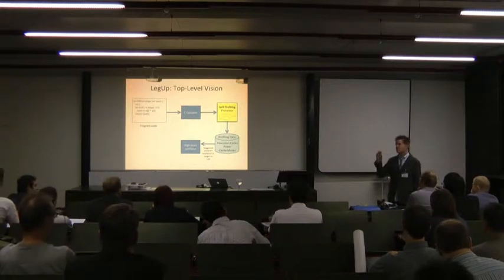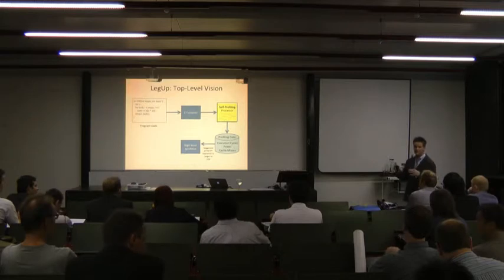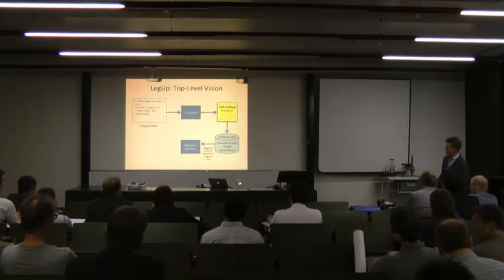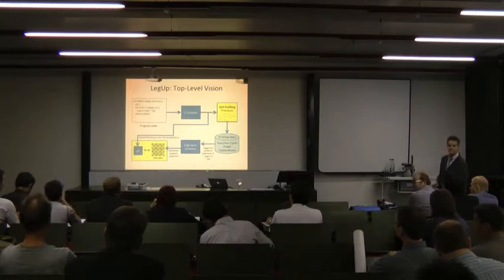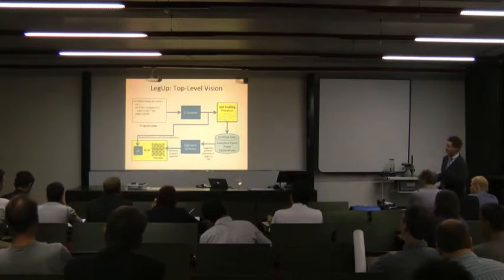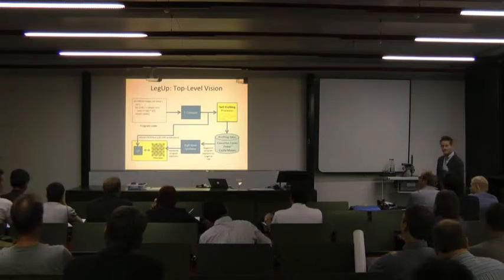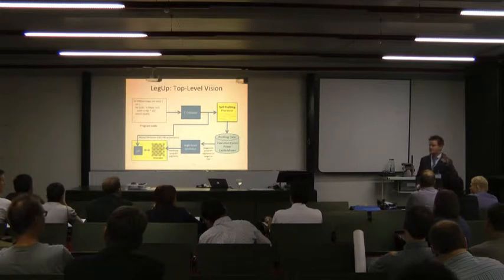So we would synthesize whole C functions to granularity. So that's the granularity that we can convert these into hardware. That goes into high-level synthesis. And then those chunks of hardware corresponding to functions in the C are implemented on the FPGA, and the computer is still there. The original versions of those functions are ripped out, and they're replaced with wrappers that call the hardware accelerators and receive data back from the hardware accelerators.